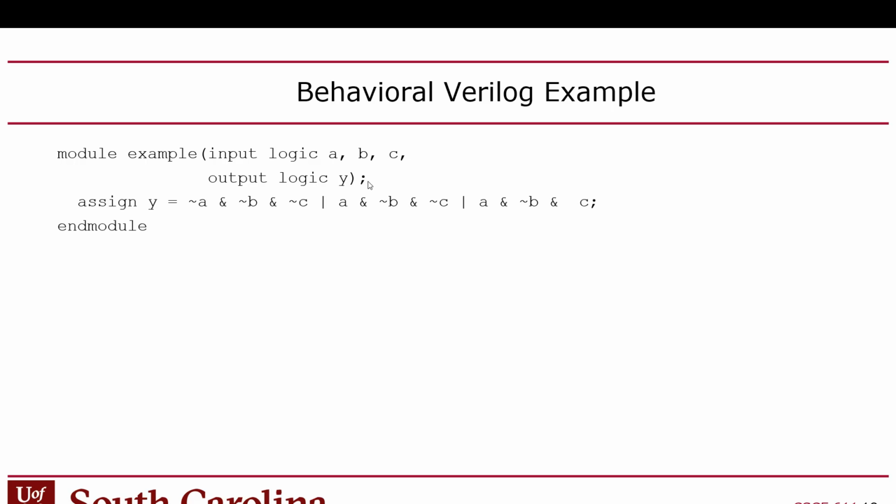There's something called a program counter inside the hardware, and it tracks where it is in the program, right? But in Verilog and VHDL, they use concurrent semantics, which means that usually, and there's some exceptions to this, which I'll cover, but in general, if you have these assign statements, the order that these are in makes no difference in the code, right? There's no notion of where you are in the code.